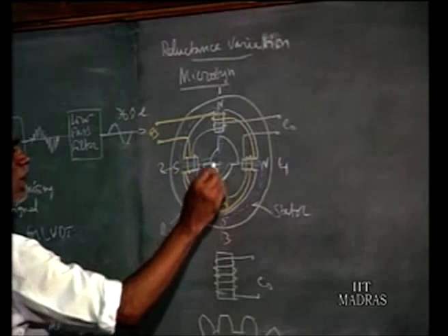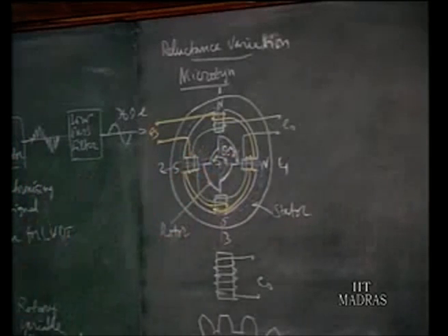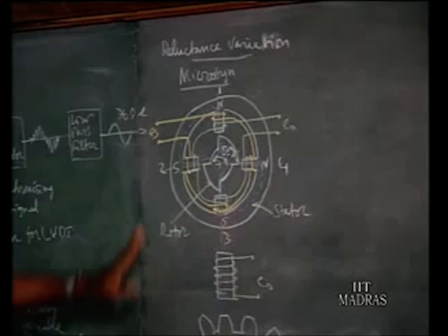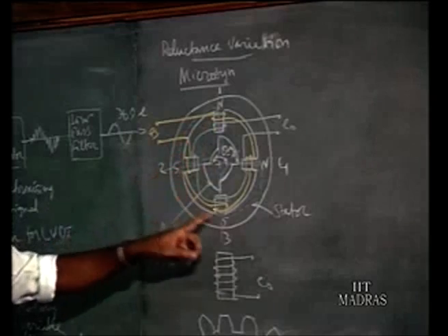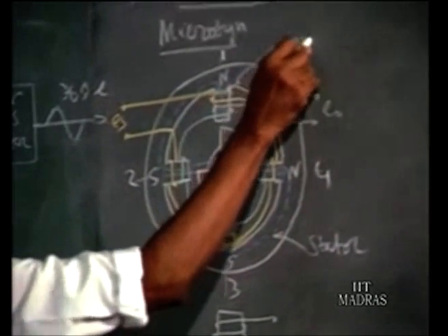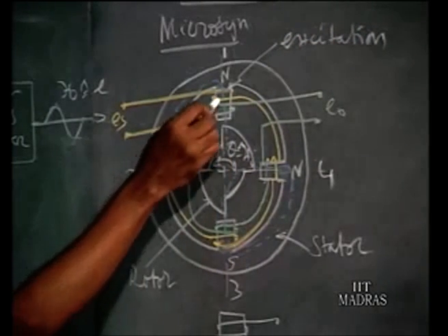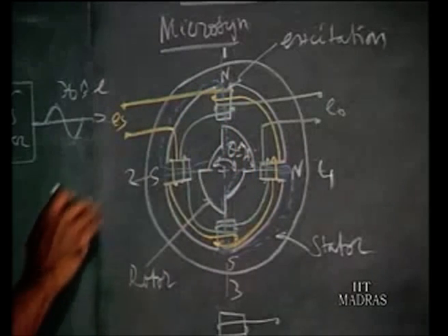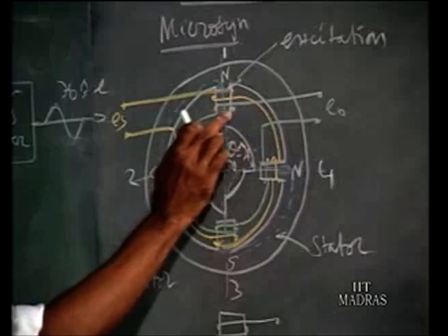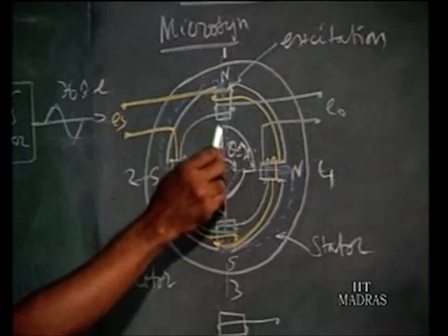So there is a rotor which can make a rotation theta, that is our input signal Xi. When it rotates, we find the resistance for the magnetic lines changes; one or two lines are shown here. The magnetic lines are induced on the poles; there are 4 poles in the stator, and there is an excitation coil. This is your excitation winding, shown here as a yellow line, and each pole has an excitation winding as well as a secondary winding. The excitation winding is similar to our primary coil in the LVDT, and the secondary winding is shown here by the green line. So each pole has an excitation coil and a secondary coil.